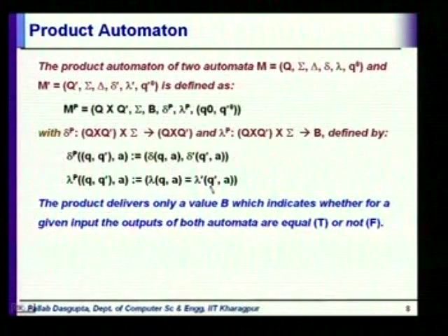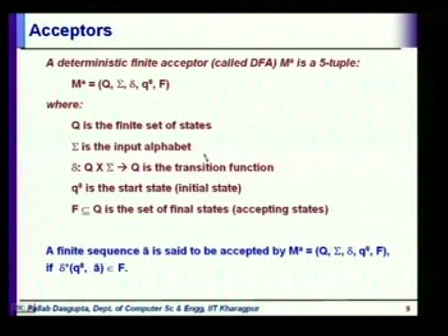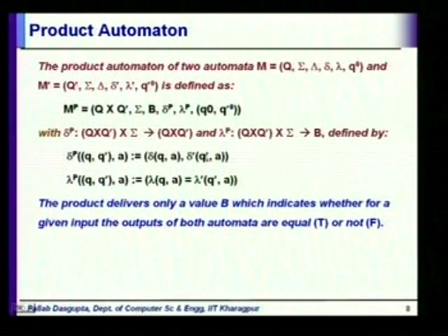All right. So can we say something about the equivalence of the two machines from this? If we take the product, all outputs should be 1, right? Isn't it? That's what we feel should be the definition of equivalence between these two state machines. Now, okay, we are going to come back to the computation of the equivalence between the two state machines. We will see that it's slightly more complicated than what it seems here. Okay, and we'll come back and explain why it is like that.